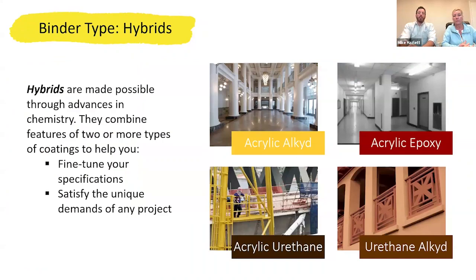In the hybrids, these are awesome kind of technologies that have come out recently. I've used several of these on different projects, even in my own home. I recently, 5 years ago, painted the cabinets in my kitchen with an acrylic alkyd, and that basically gave me the best of both worlds between a latex paint and an oil-based paint. So it gave me that durability and that hard, smooth finish of an oil, but it also gave me the soap and water cleanup, the faster dry time, and virtually no odors of a water-based.